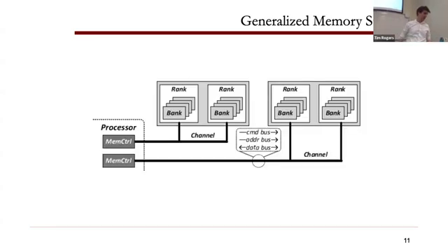Okay. This drawn another way looks like this, where this is a system, a processor that has 2 memory controllers, so 2 different channels, and then this has 2 independent ranks. So a DIMM usually looks like this, where we've got 2. The front side is 1 rank and the back side is another rank.